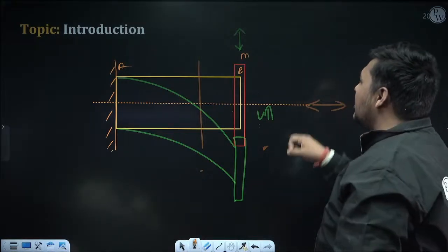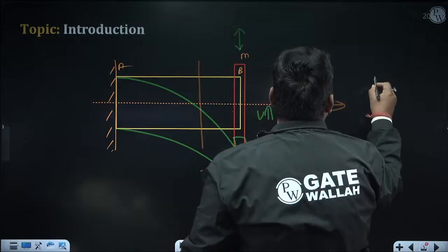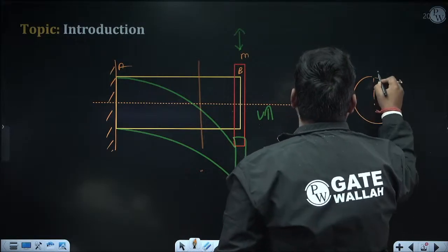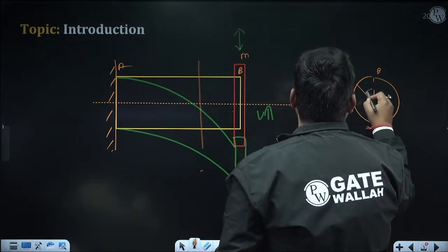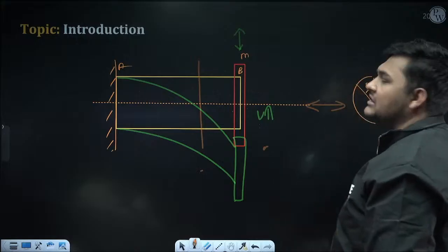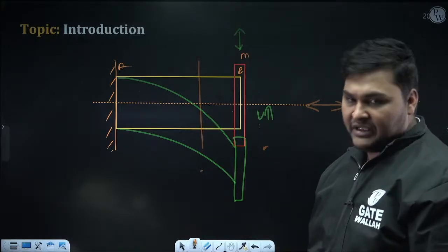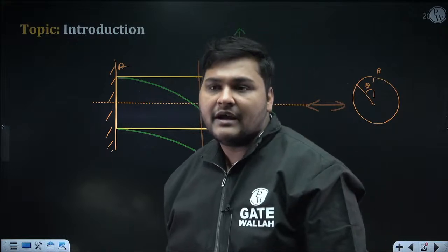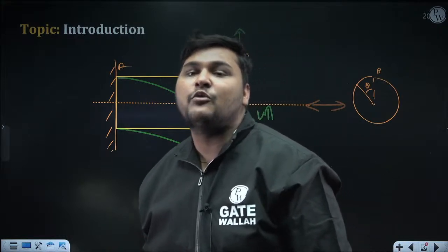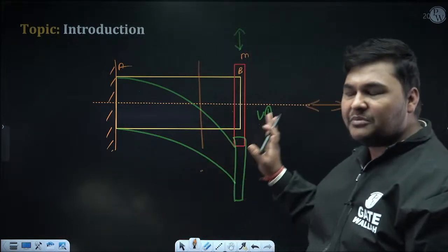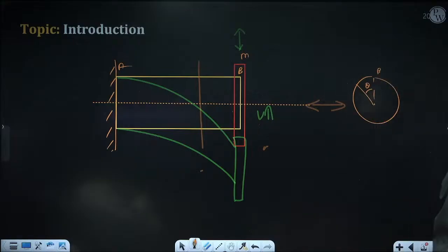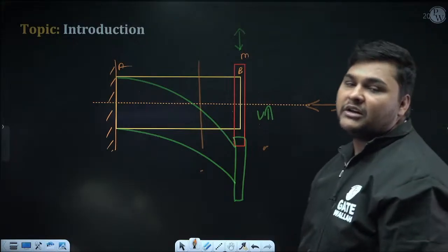So can I say if we disturb the rotor like this, twist will be created in the shaft. Twist will be created at B like this. And due to that twist, torsional stiffness will come into the picture, and that torsional stiffness will provide a restoration. How to calculate torsional stiffness, that we'll discuss later, don't worry. But here torsional stiffness will provide restoration.